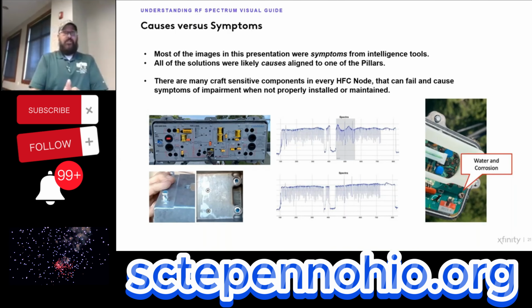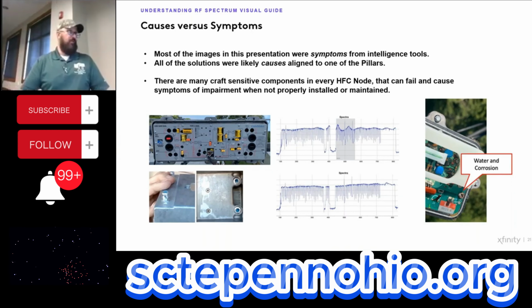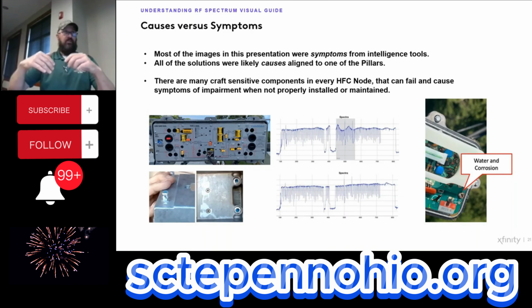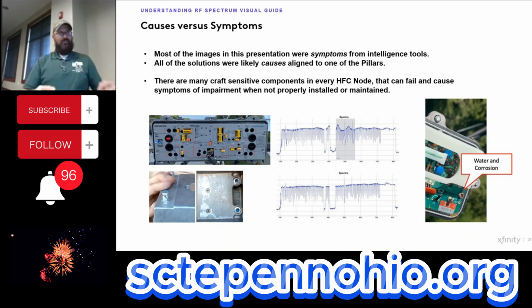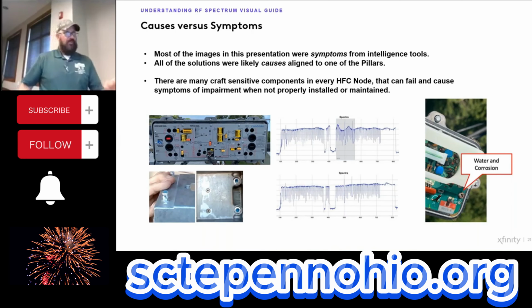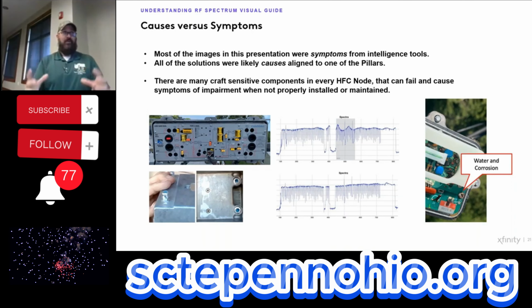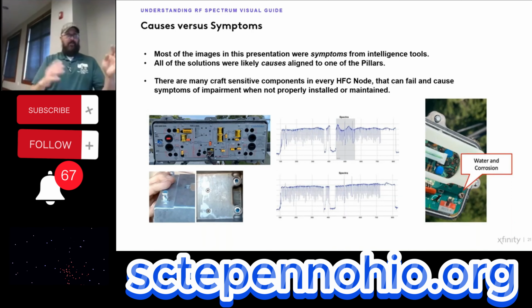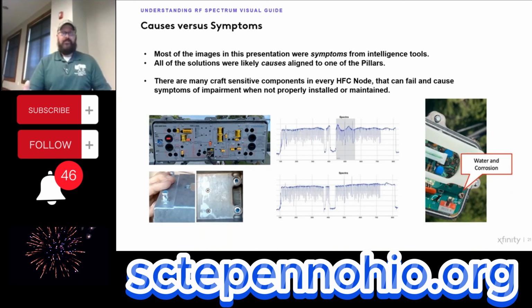But the physical cause is the holes in the jacket that were caused by the power line that came down or whatever. You look at the squirrel, you look at a drip loop that was poorly formed over years, right? And sometimes you can tell even underneath the strap, you can see the cable is a little sharper than it maybe ought to be, right? There's likely a crack underneath of that strap. Now that's a shielding integrity breach. It's also an impedance mismatch. So now we're into that compound impairment category, right? We've got that radial crack that's allowing ingress in, but now it's also creating these reflective cavities of different sizes depending on where the crack is.